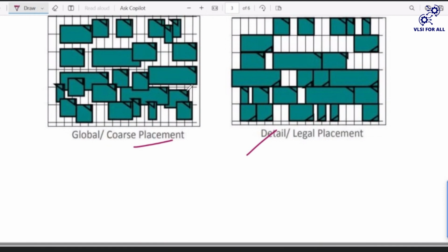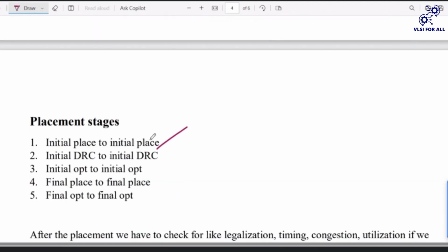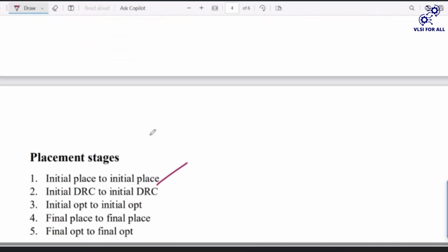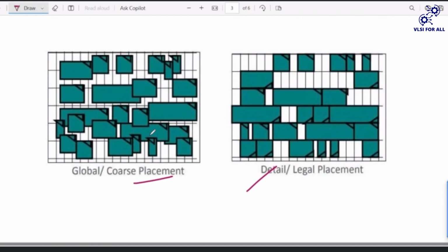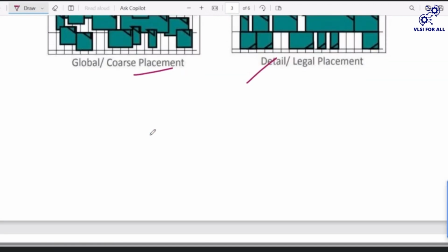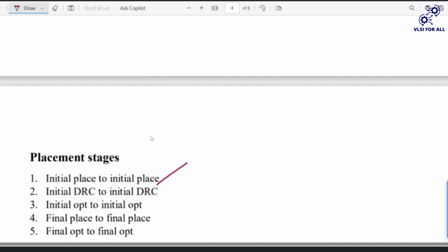All the standard cells are not placed at the exact site row, and there may be overlapping between them. Scan chain optimization also happens in this stage, and buffer-aware timing also takes place. Wherever the timing is not meeting in a path, buffers are added.